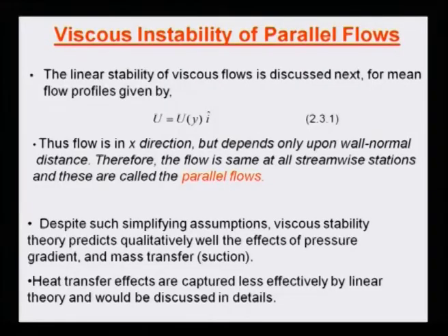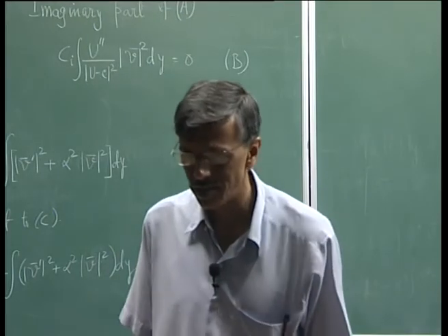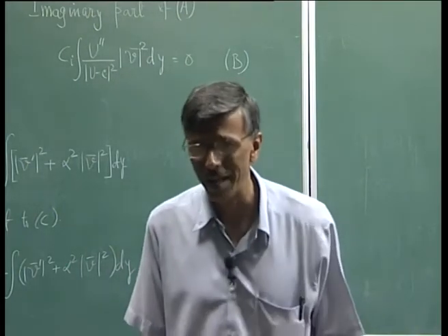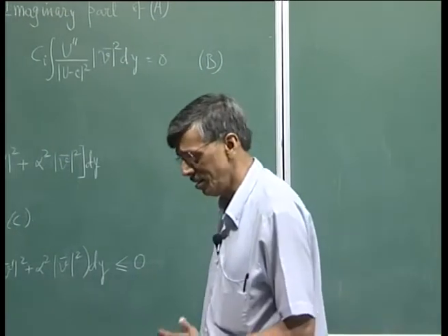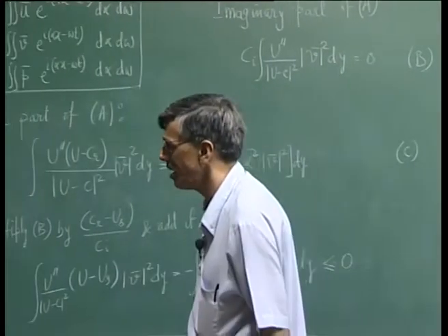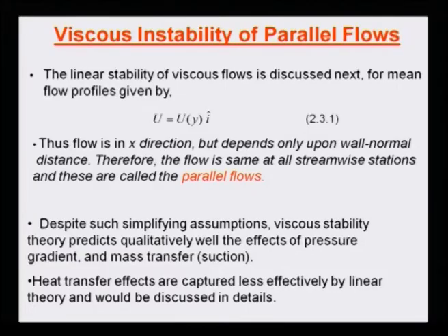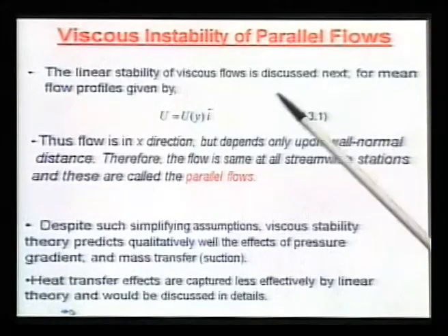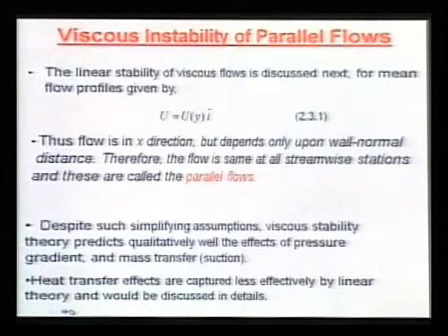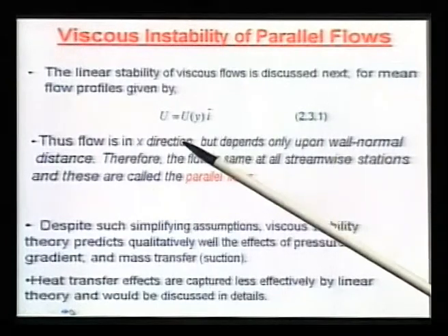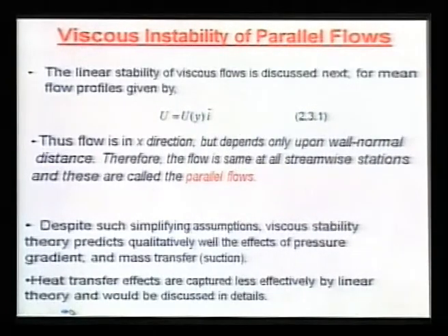What we are doing once again, we are looking at linear stability, that means the perturbation fields are small. So, in deriving the disturbance equation, we would make the small perturbation assumption and omit the nonlinear terms. However, we retain the same equilibrium flow description. The mean flow or the equilibrium flow is once again given by a parallel profile, right.